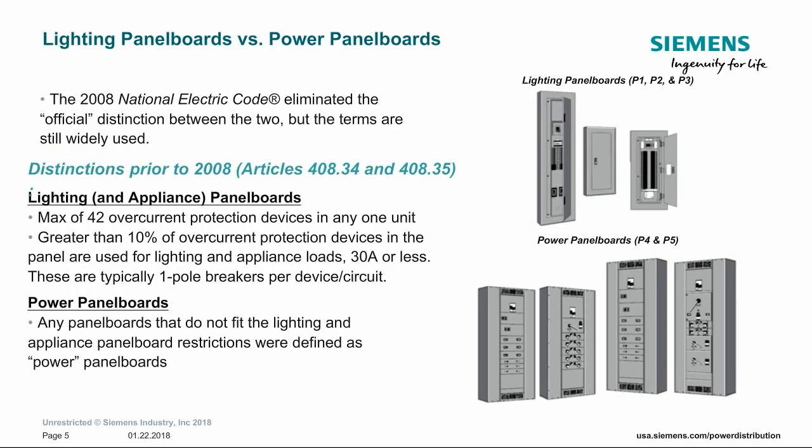Now that you know what exactly a panel board is and how it fits into a typical electrical distribution system, you may still be wondering one thing. What exactly is the difference between lighting panel boards and power panel boards? Well, the 2008 National Electric Code actually eliminated the official distinction between the two, but the terms are still widely used in industry today. So the distinctions prior to 2008, which were defined in Articles 408.34 and 408.35 in the NEC,